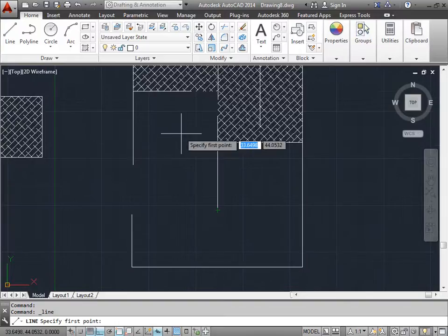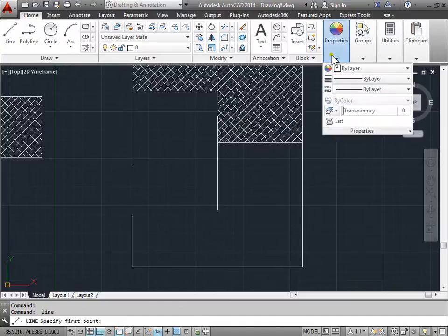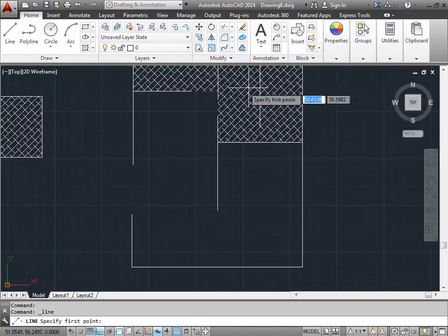But if you want to take a shortcut and you know the tolerances that you can use so that it wouldn't conflict later with your hatching, you can go ahead and adjust that in your gap tolerances and then add the hatching to each individual area.